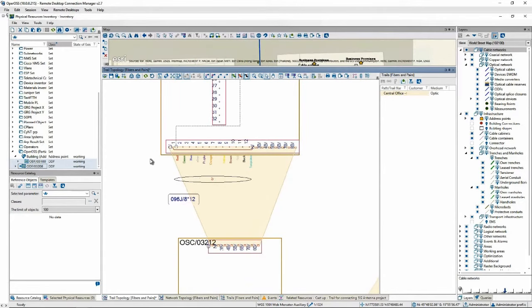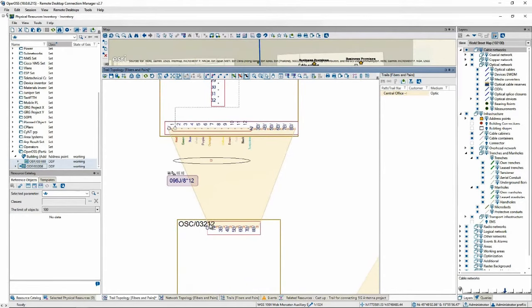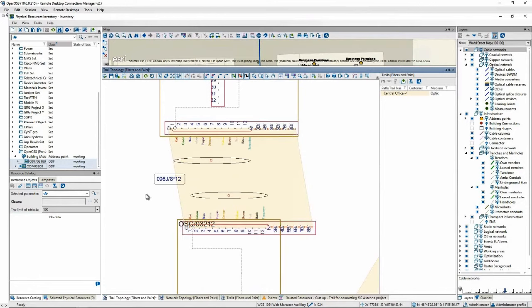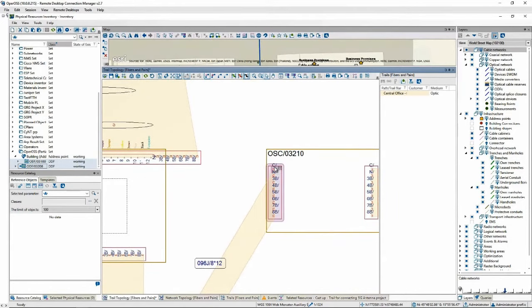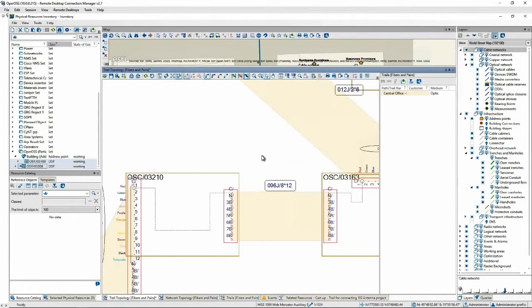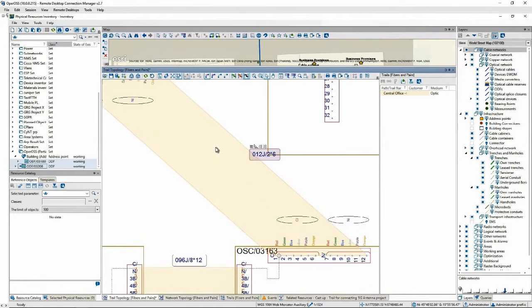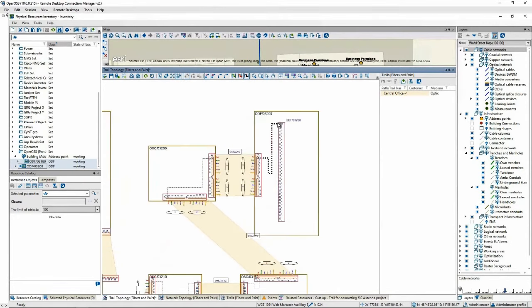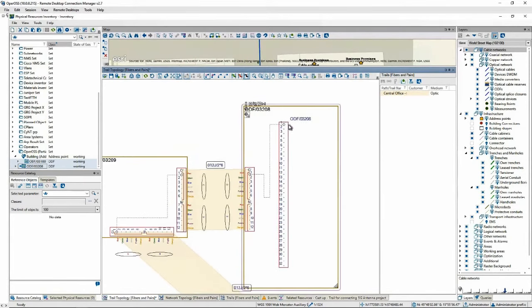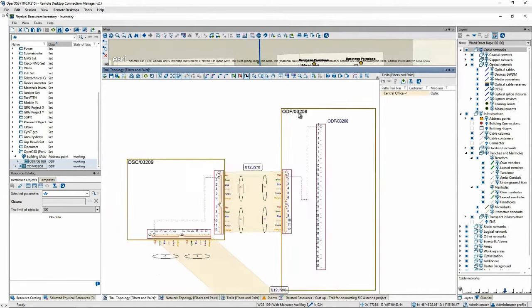And therefore, we are also able to see other elements and other cross connections on the path. So I'm just showing and expanding these cross connections to see it from point A to point Z, where point Z represents the ODF and first port in the patch panel within the ODF on the 5G base station side.